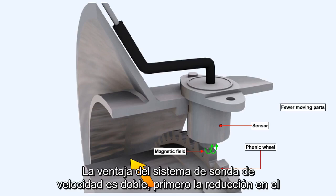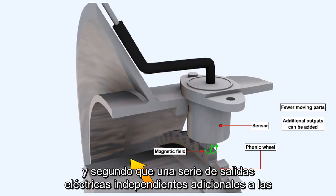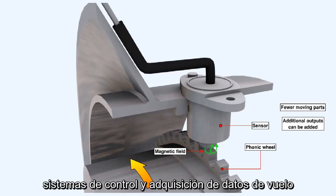The advantage of the speed probe system is twofold. First, the reduction in the number of moving parts required in the engine, and second, that a number of separate electrical outputs additional to those required for speed indications can be provided, for example, automatic power control and flight data acquisition systems.